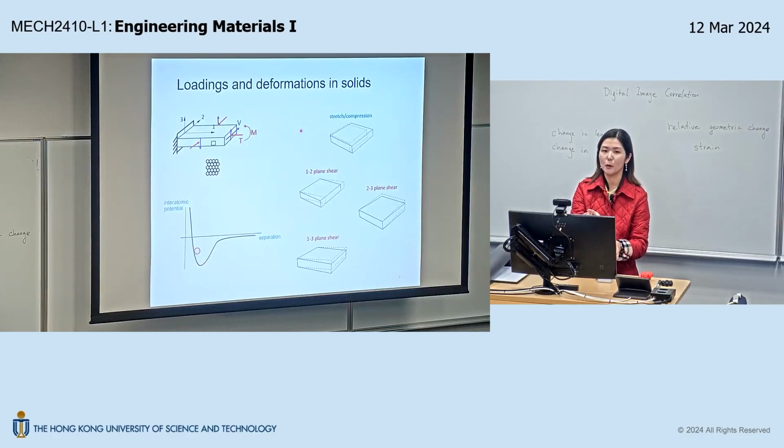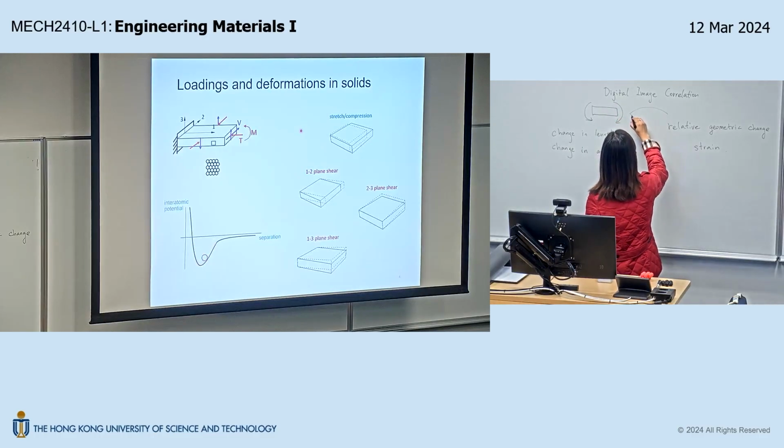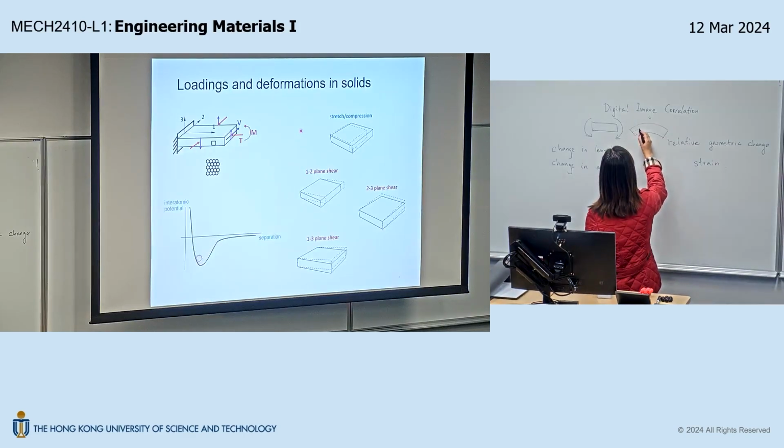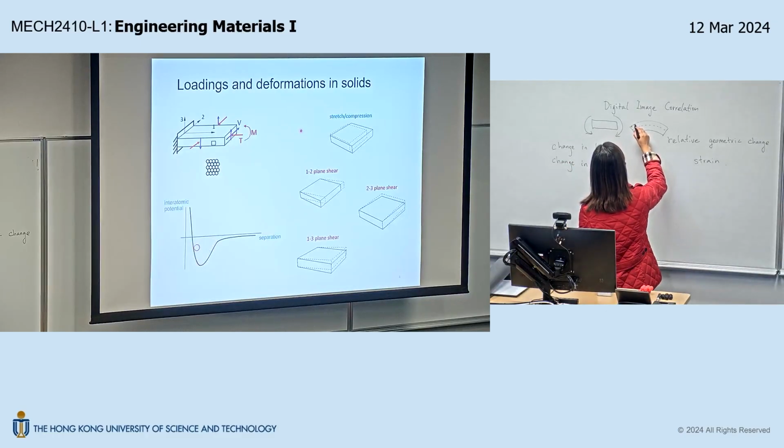How about moment? Moment gives you all. Moment gives you this kind of thing. So if you have a bar here, and then you apply the moment like this, can you imagine how it deforms? It deforms like this, right? And then you have a central line that does not extend or contract, and all the particles here are stretched.